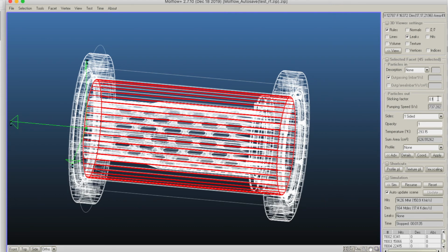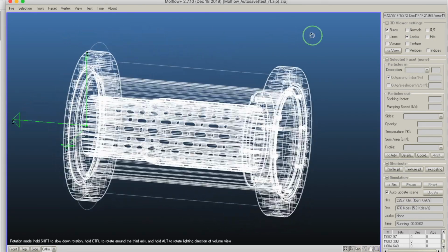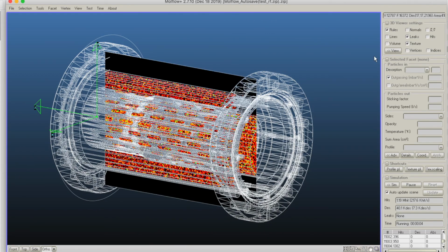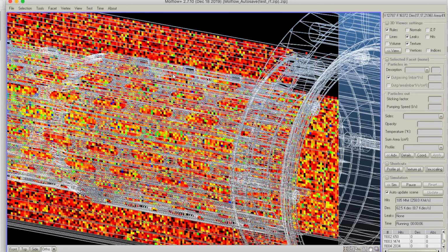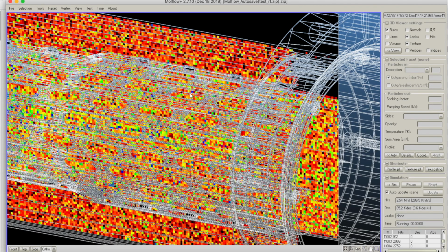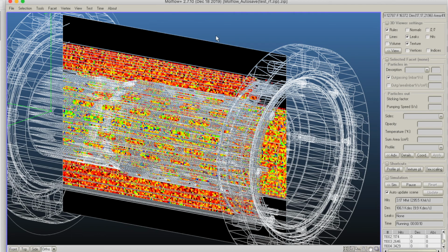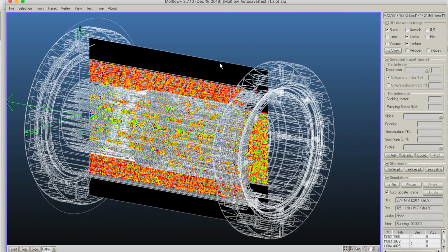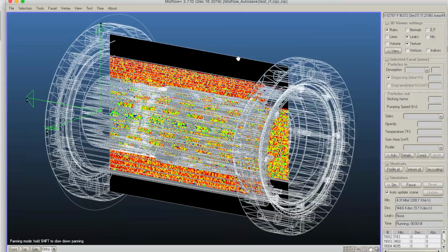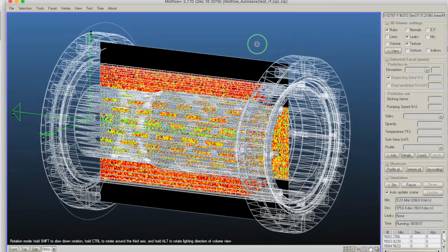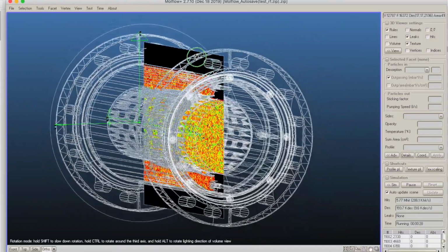And let's check if we still get the same result if we change the pumping speed. If conductance is indeed only dependent on the geometry, we should get exactly the same value, so it's worth playing with it a little bit. So let's go back to our calculations. Since our pumping is lower, the pressure difference between the inside and the outside is now much lower, and that's why we would need to run a longer calculation, typically for, let's say, 20 minutes, depending on your computer.